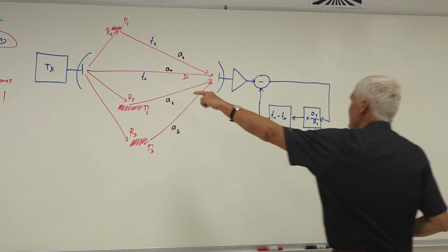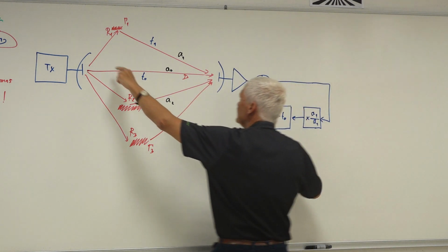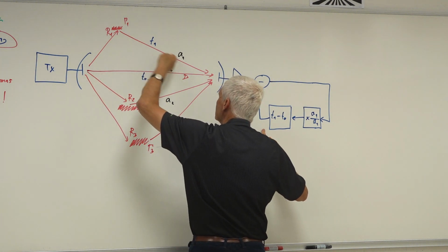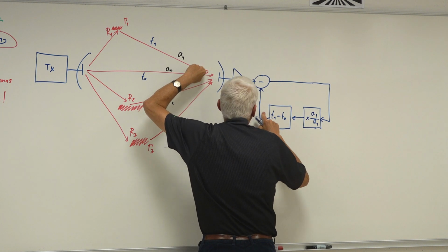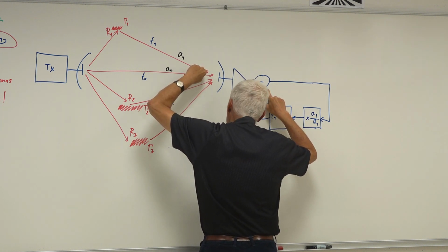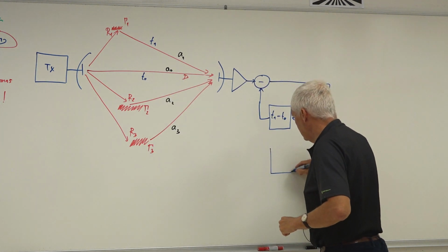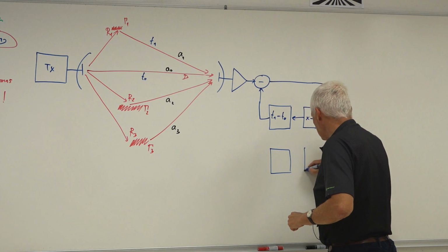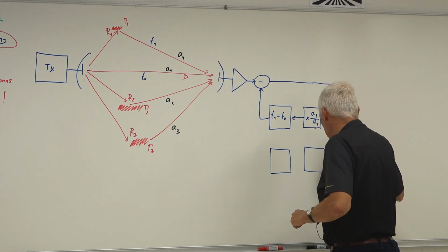So first I get the direct signal, I delay the direct signal here, but I also delay the same signal over this refracted path here. If I flip the polarity of this one here, I can exactly cancel out this reflection signal here. I do the same for the other reflections. So for reflection 2, I do the same kind of processing here.